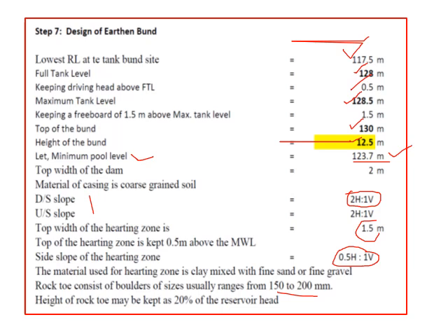There are a few formulas for fixing the preliminary sections of the earthen bund. You can refer to those preliminary sections for the earthen bund, and then decide the top width. Also you can decide the freeboard, and then you can use the slip circle method to decide the slope. You can do a number of trials for the earthen bund and see that you get a safe factor of safety, which will be more than 1.5.